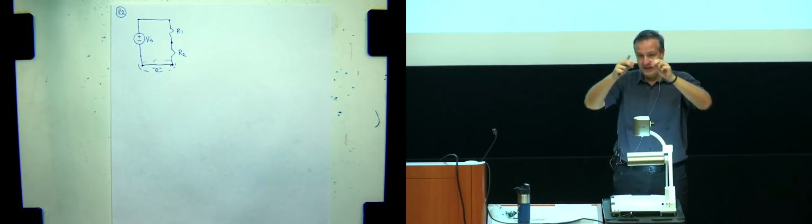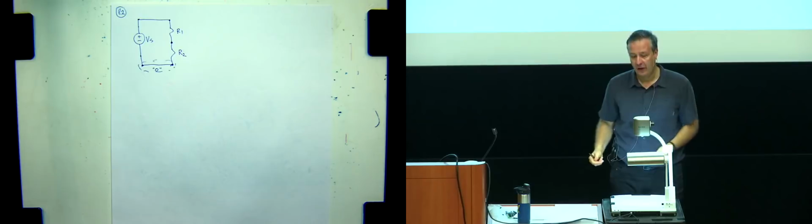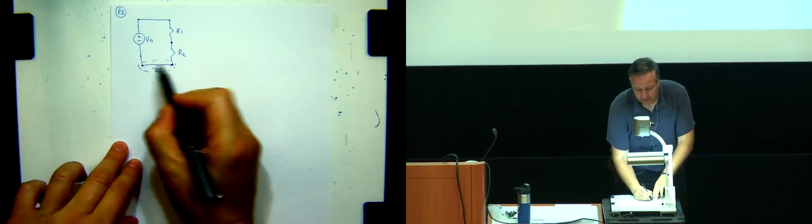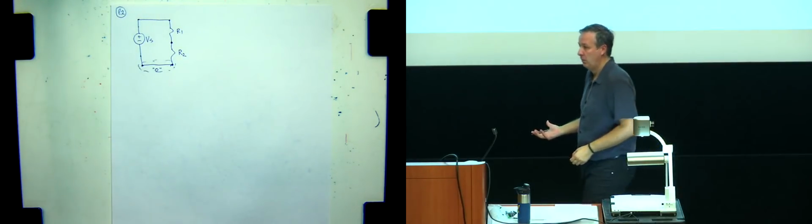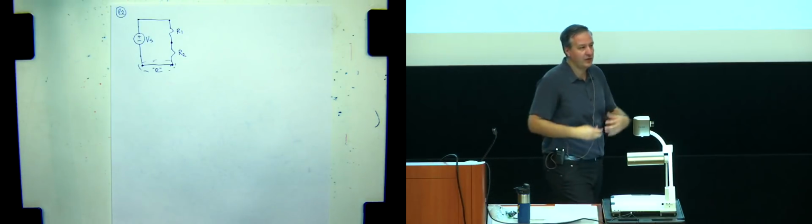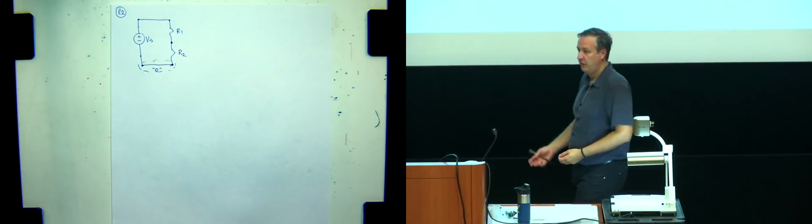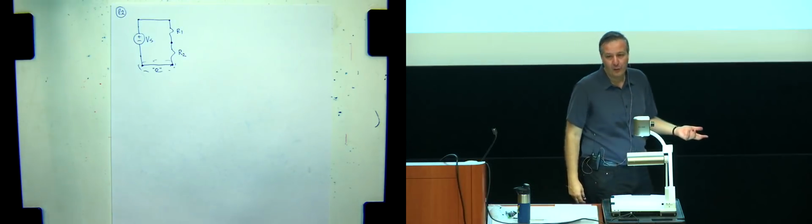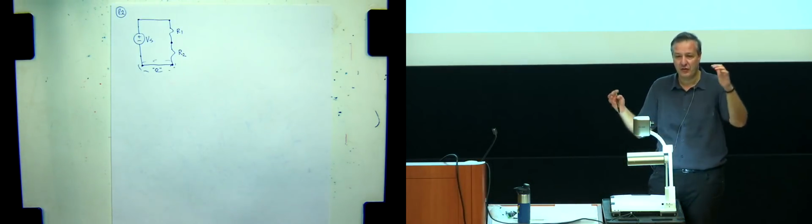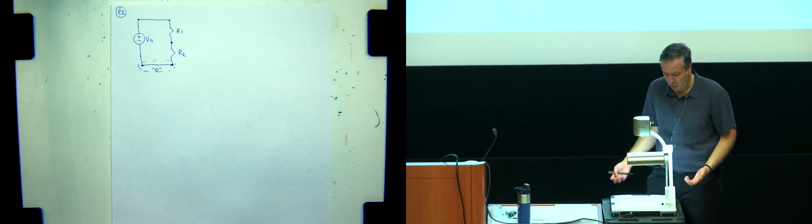It has the same potential along it. In other words, the voltage between these 2 points is 0. That was the definition of the wire as an element. So I can treat that whole wire as one circuit node. That simplifies the number of variables I have to carry. I don't have to carry the potentials on both ends of the wire because I know they're the same value, so it makes my matrix a little bit smaller when I'm solving.